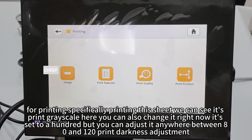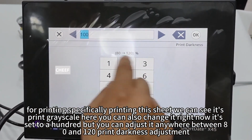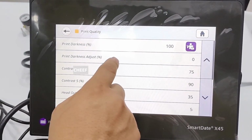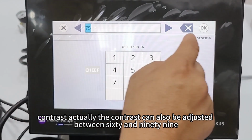For printing, specifically printing this sheet, we can see its print grayscale here. You can also change it. Right now it's set to 100, but you can adjust it anywhere between 80 and 120. Print darkness adjustment. Contrast can also be adjusted between 60 and 99.